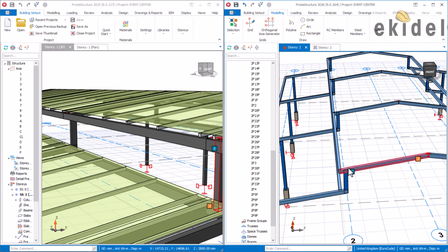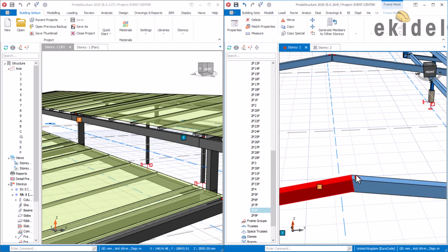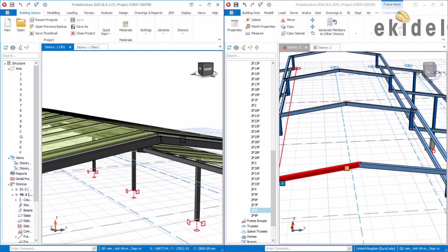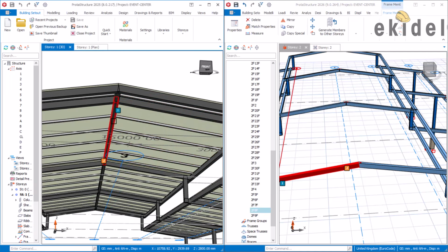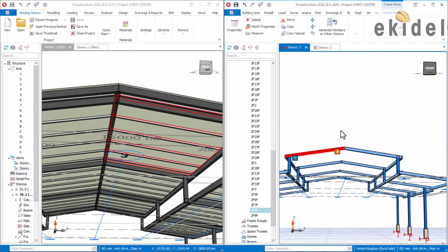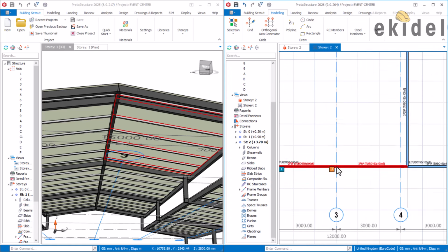Next, there's a central beam that's going to connect here that will make these ones go out to be a cantilever. So we have to do that here, which will be this particular beam here. That's correct. So let's now model this beam at this particular level. Go to our plan view now, and on the plan view that beam is found at the center here, around the centers.